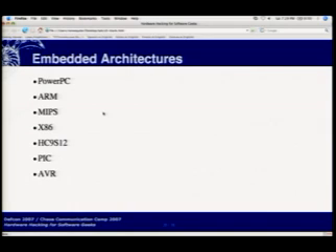If anybody caught Bunny's talk at ShmooCon 2 years ago, he basically decapped a chip, removed the plastic from the top of it, and then shone UV in at an angle to get under the aluminum layer that was covering the fuses that were set when the chip was set to be write only. And that way managed to clear the fuse and dump all the code out of the chip. Needless to say, that's not a very easy operation. It's doable, though, but not something a noob should attempt. Yeah, he used a lot of acid for that to etch the chip top off.